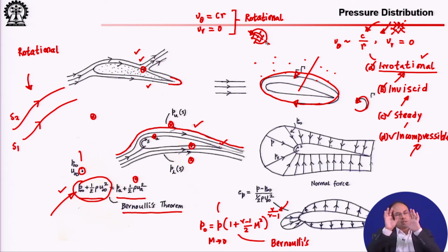When we say rotational flow field, we really mean that the fluid elements are rotating around their axis, almost like a solid object, but because it deforms while it rotates in most cases, the rotation of a fluid element is defined in a slightly different manner.